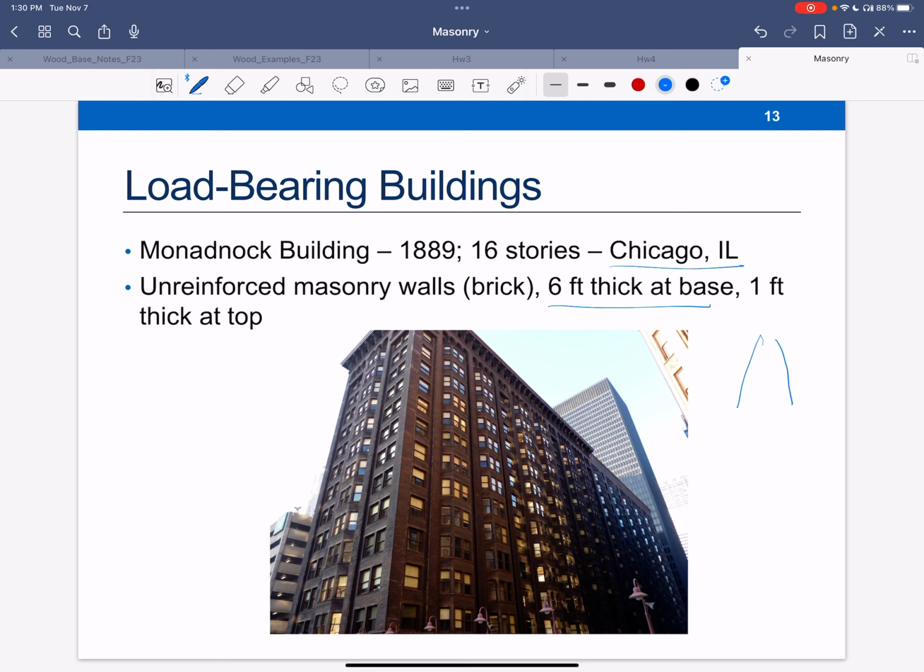This is in Chicago. I went to undergrad and got my master's degree in St. Louis. That is in a high earthquake zone because of the New Madrid fault. At the time, nearly every building in that town, a very huge part of the infrastructure there, was built around the time when unreinforced masonry was widely used. We weren't considered a seismic zone, and so everything was unreinforced masonry. Same with Memphis. Since that time, they have retrofitted a lot of those buildings, and today, if you're in any seismic risk area, you definitely would not have an unreinforced masonry building. It's going to crumble like stone.